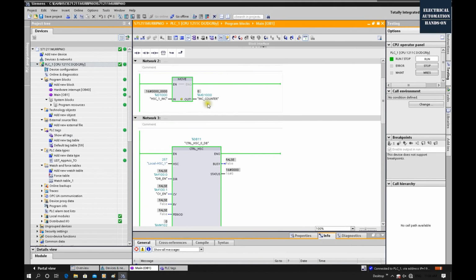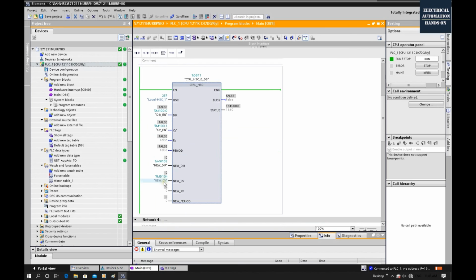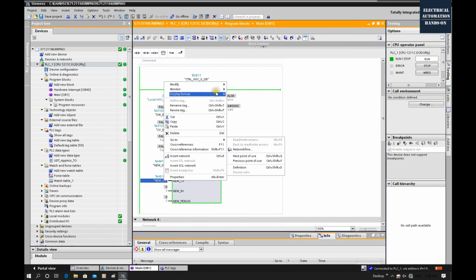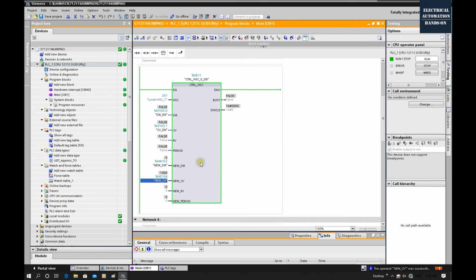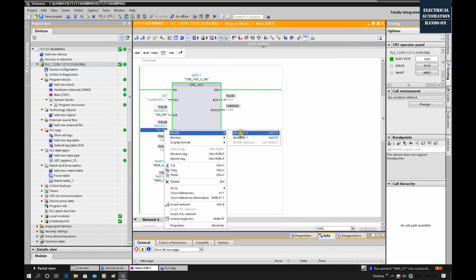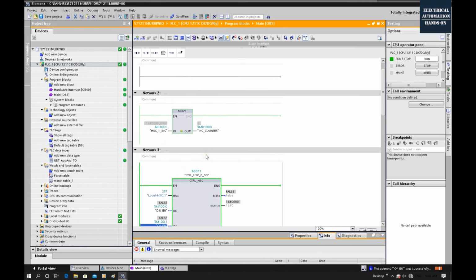And after the download, we can see the initial value is 0. So now we can preset this counter value. If we go to this new CV here, and if I set, for example, 1000, prepare the 1000 value here and trigger this CV, turn this on. And in the meantime, we can see the output BZ here, it doesn't show any fault. And then we can go back to the counter. So we can see the counter preset 1000.